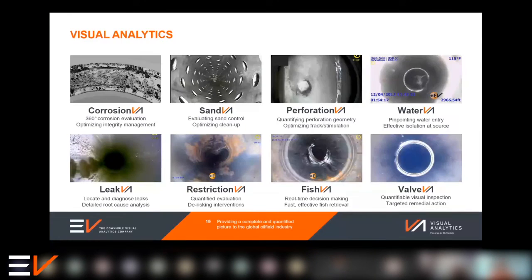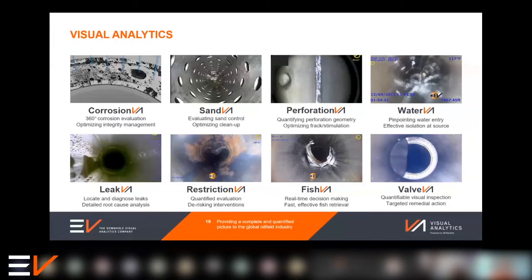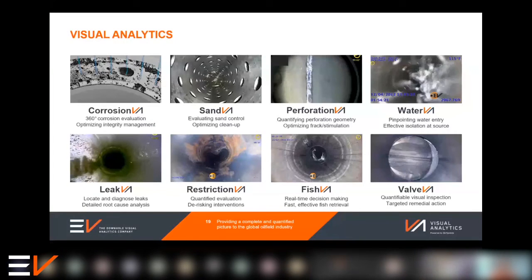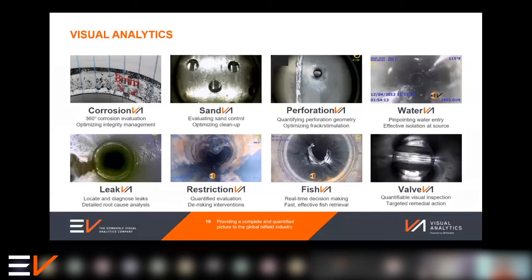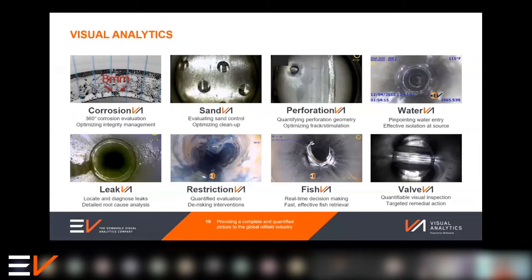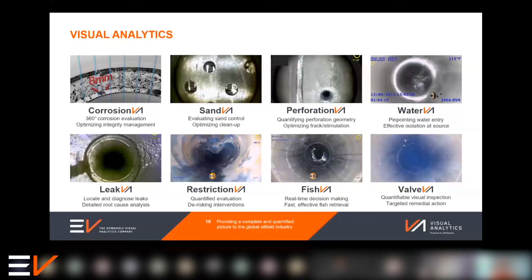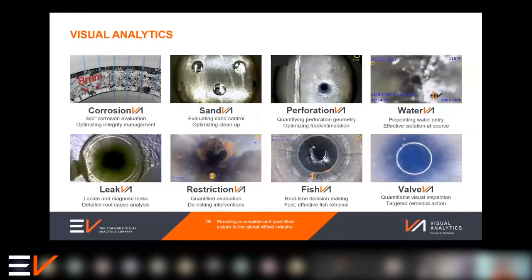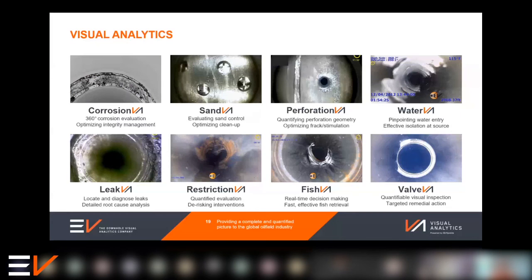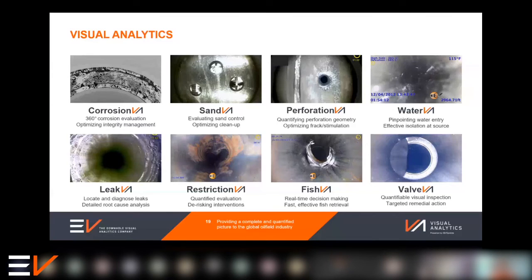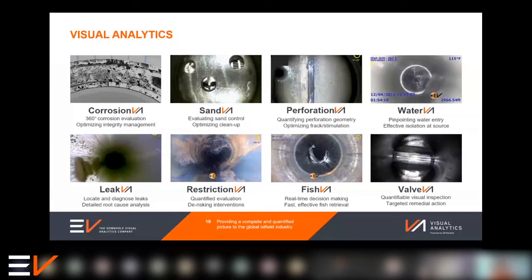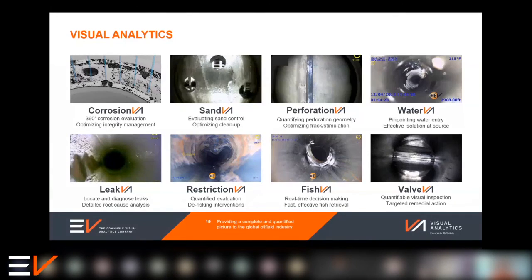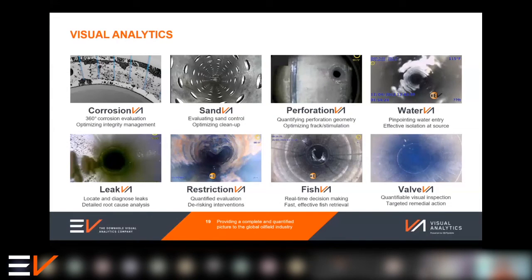Yes, that's a great question. We have video systems that go up to 200 degrees Celsius. They are time limited because we've put them into a thermally isolating flask. But we use those extensively for HPHT operations in the oil and gas environment, but also actually a lot of the time in geothermal applications where the well temperatures are way above what we normally expect in the hydrocarbon industry. So we have those variants available in real time up to 200 Celsius and up to 160 degrees Celsius in memory mode at the moment. And we expect that we'll push that envelope further as we go on.